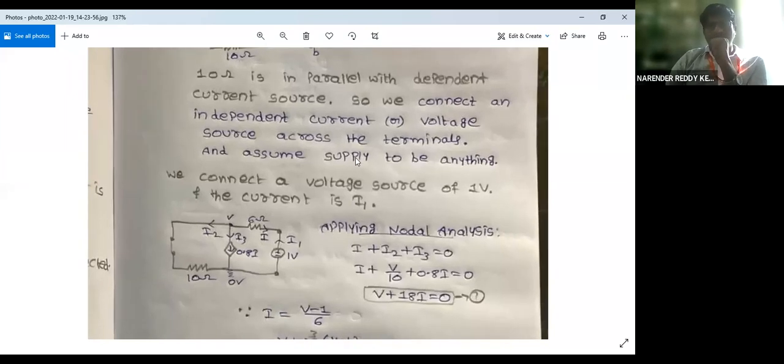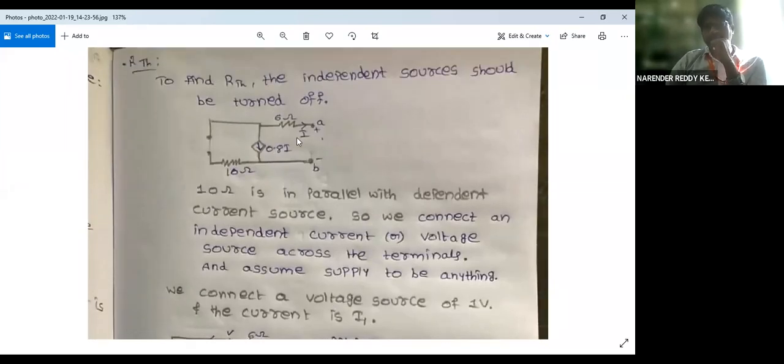So in yesterday's assumption, if we assume this to be a current source, and I replace the voltage source with a short circuit here, what should I do with the current source? I should open circuit this, right? So the equivalent resistance could be directly given as 6 plus 10, that is in series here. But the problem is, according to the statement of Thevenin's theorem, the dependent sources have to remain in the circuit and cannot be changed while finding the value of RTH.